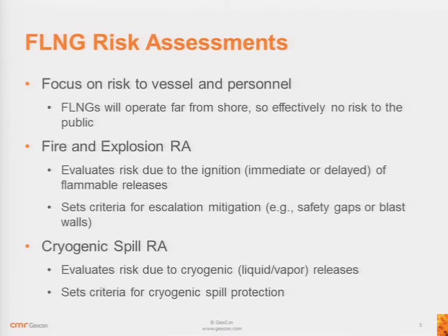You can do a lot of damage if you have a cryogenic spill in an area that is not properly protected. So the goal here is to figure out what we need to protect, and what's a compromise, because obviously you could protect your entire FLNG against cryogenic releases.